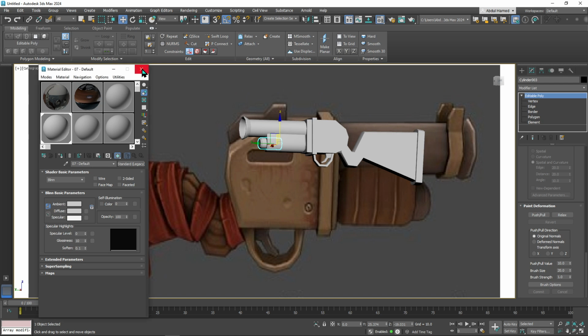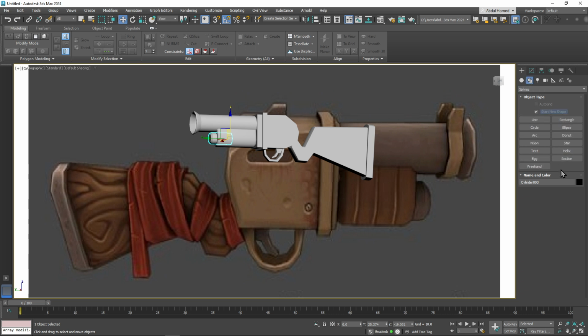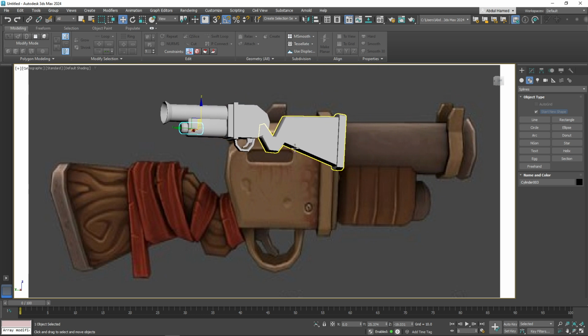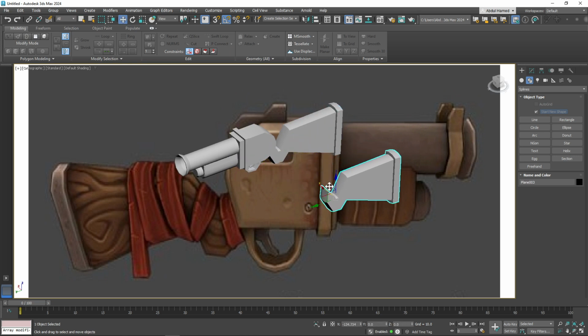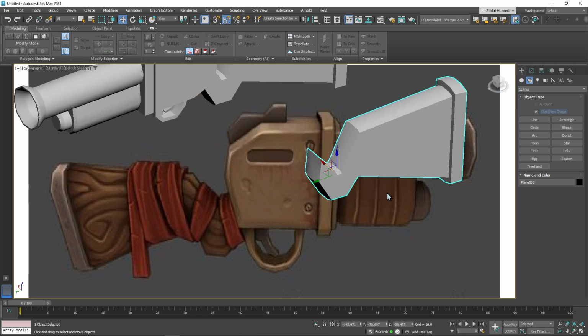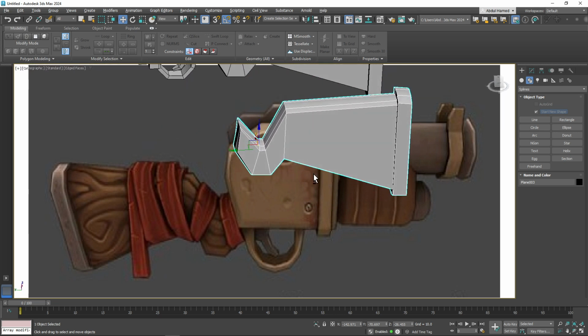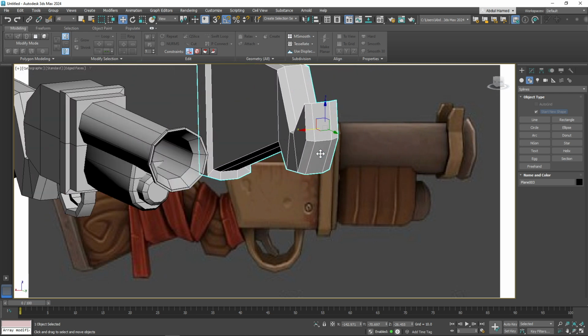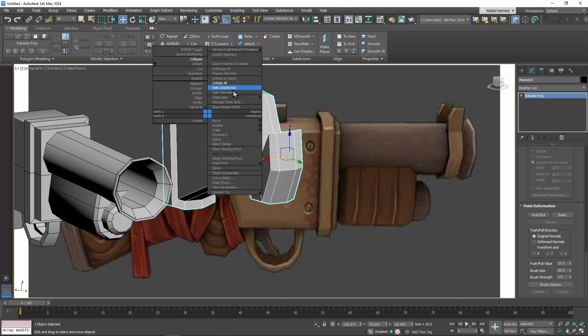So how about this right here, the cloth? You can do this with a line using a spline tool. This will require a lot more work. One way of doing it is to take this object, make another copy of it, and just draw the line in so we can see. And now using the knife tool, let's go into edit. Let's hide everything, hide and select it.